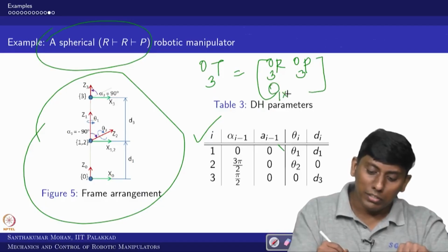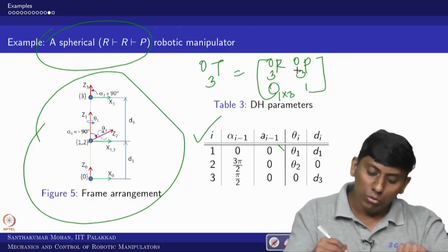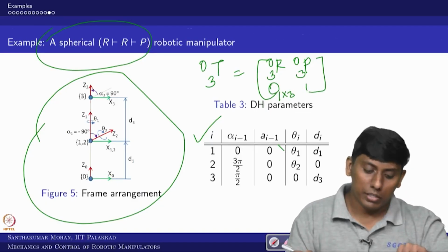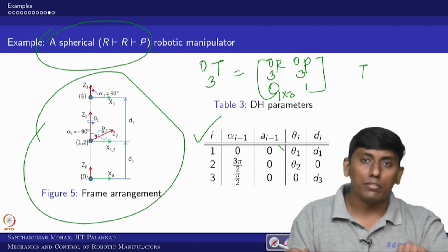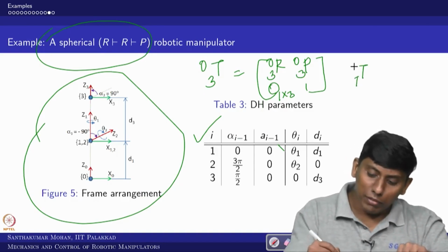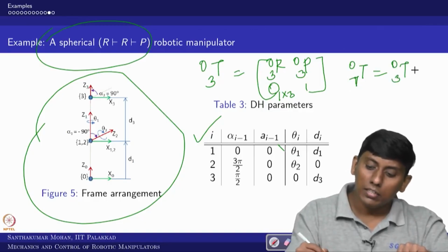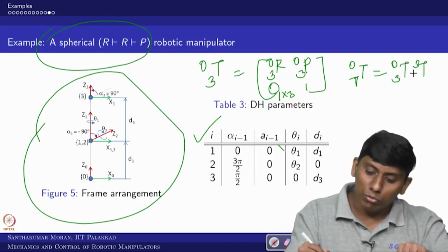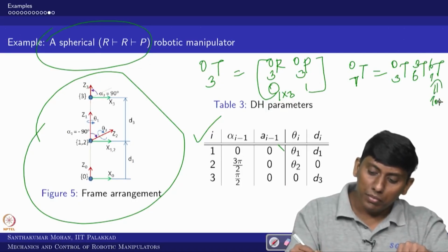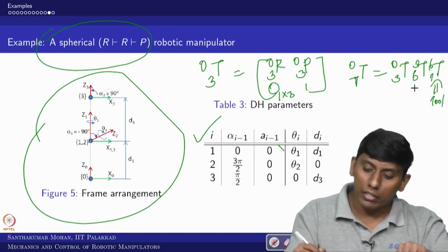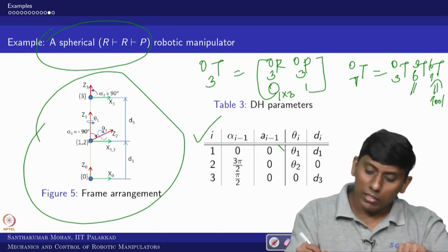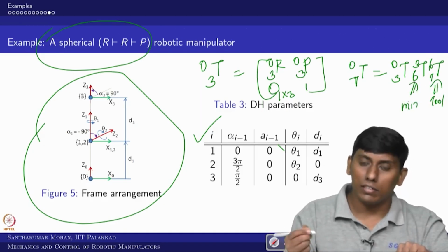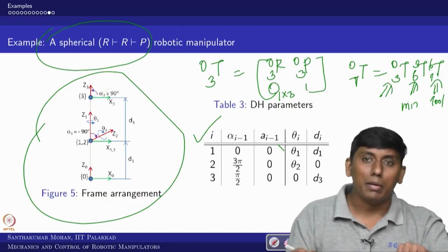So these we have all seen. Now, since it is a 3D system and it is going to give a major axis, because we have seen the transformation matrix of 7 with respect to 0, we can simplify it as 0 to 3, then 3 to 6, and 6 to 7. This we call the tool orientation vector or matrix, and this is the minor axis transformation, and this is the major axis.